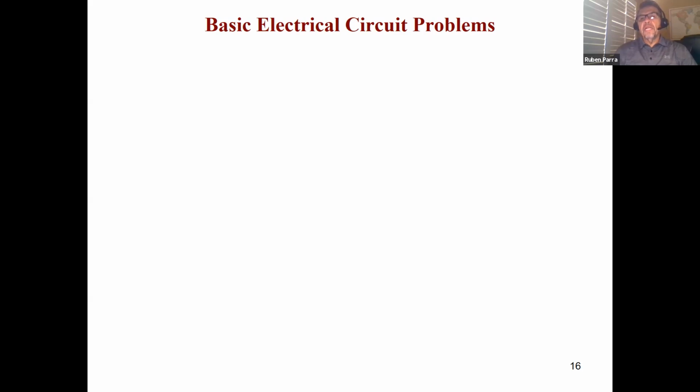Whenever you're working on an electrical problem, remember, 90%, 9 out of 10 times, if you work on 10 cars with electrical problems, 9 of the times it's going to be a power or ground problem, right? Keep that in mind whenever you're working on any electrical circuit. So we always make sure that we have proper power, proper ground. If we have that, then we move on to the circuit. Our diagnosis goes in that order as well.